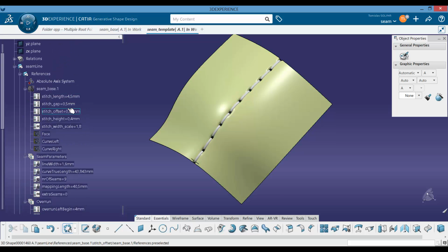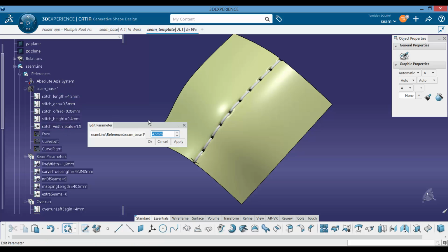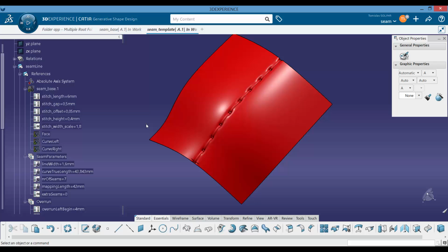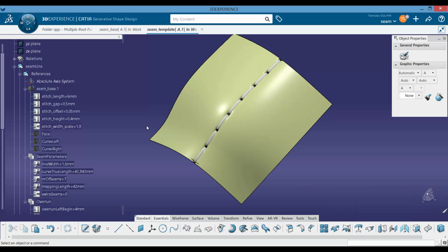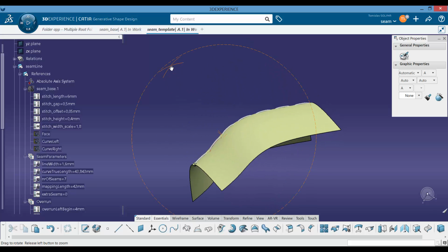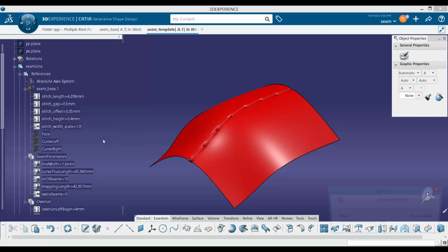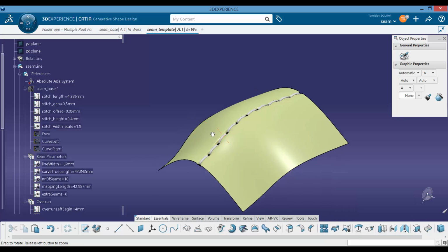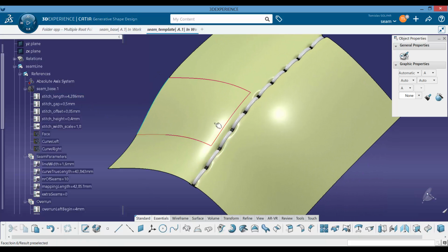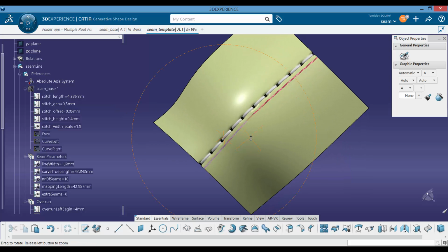In case that you want to play with other parameters, feel free. So if we change this 4.5 to 6 and update, we'll have slightly bigger elements, less of them, and our template will survive. But as we are using relative standard, standard was actually 30 divided by 7, which was the desired result for interior in the car industry, and this was given as 4.2 millimeter per length of the object. We can use this number as well.